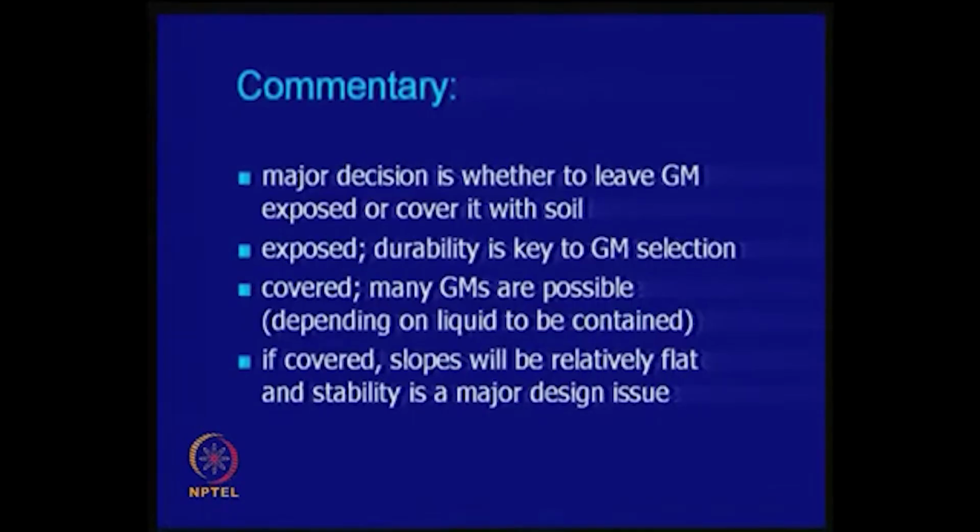Sometimes the geomembranes are quite tricky to deal with, whether to leave the geomembrane exposed or to cover it with soil. If you expose it, durability is the key. If it is covered then it is fine, and it also depends on the type of liquid you have to address. The waste industries have different types of waste, so the material should be compatible, like it should not get spoiled when it comes in contact with that chemical.